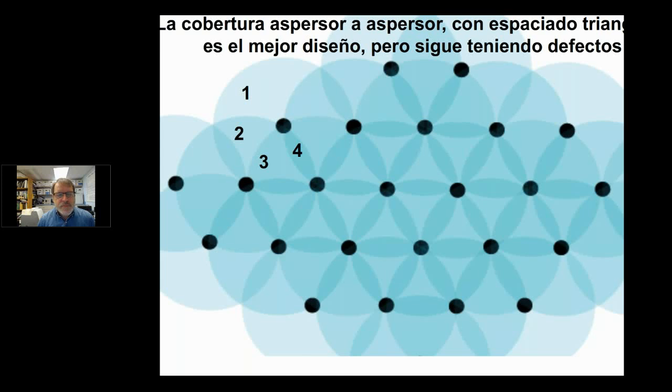Xavier Millet is a golf consultant. He is asking what distribution uniformity would be acceptable for you of sprinklers on a clay soil? Oh, well, yeah, on a clay soil, the best that you can get is what you want, but I think probably precipitation rate is going to be the big issue. You want the distribution to be around 80% if you can get it, but you definitely want to slow down precip, use low precip rotors rather than a standard sprinkler if you can, and then if possible, you would want to try to top dress to be able to apply more water.